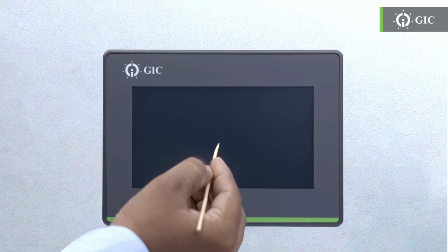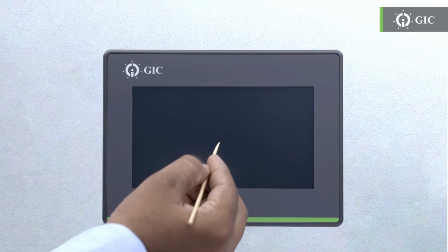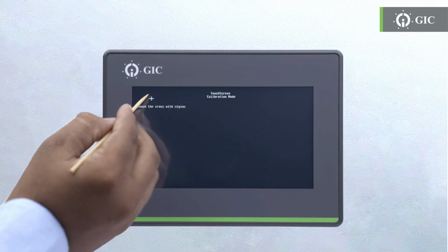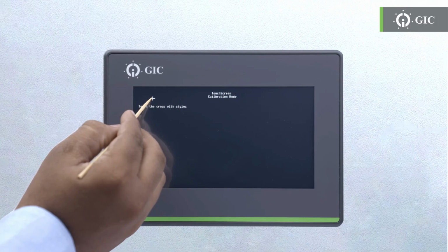Step 1. Power off the unit and press and hold the center of the HMI for 3 seconds. Step 2. Now, power on the unit. The device has entered the screen calibration mode. Press the plus sign on the upper left corner.